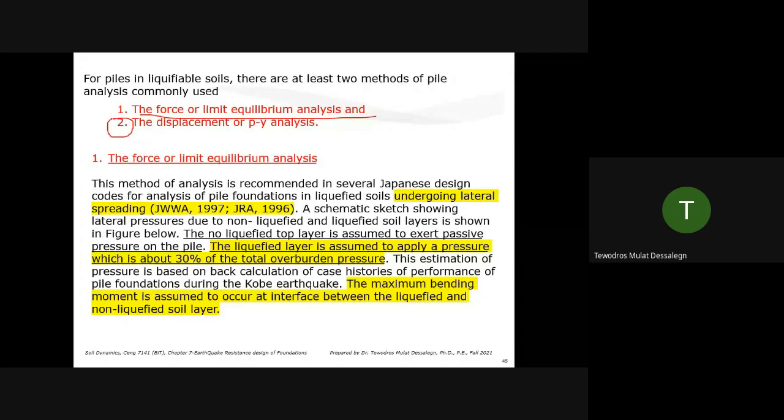But if it liquefies, it's turning into semi-liquid. So for liquid, like something like water, spring is very soft. You can't really depend on it. So the PY approach makes those springs softer. Significantly, like around 80% reduction on those springs. There will be some resistance still, but a huge loss.